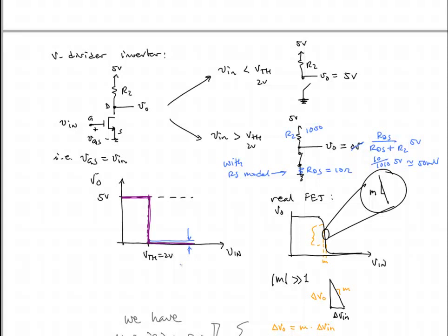And so we might want to use a static discipline for this type of logic inverter that says, okay, my guaranteed VO low is going to be 200 millivolts. I think I can reasonably get under there with this MOSFET. And of course that would depend a lot on, is your MOSFET really at 10 ohms when it's on, or does that vary from MOSFET to MOSFET? If your circuit is sitting at 100 degrees Celsius, maybe the resistance of that MOSFET goes up to something larger.